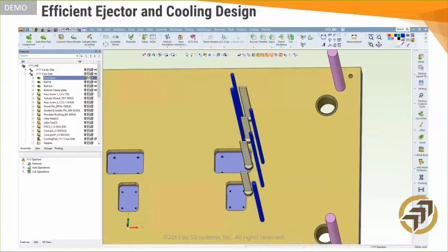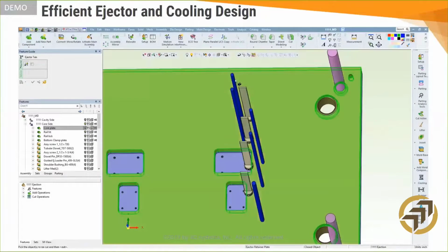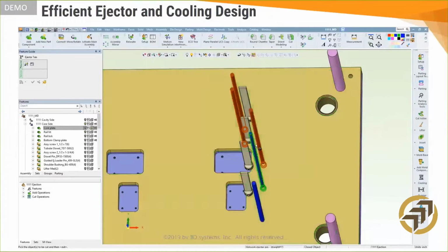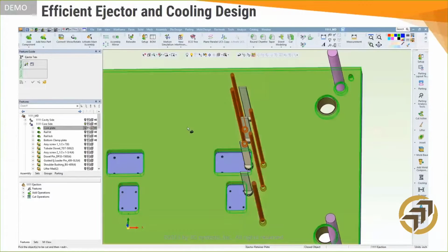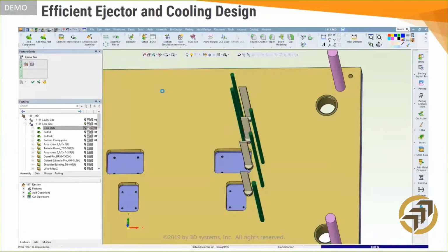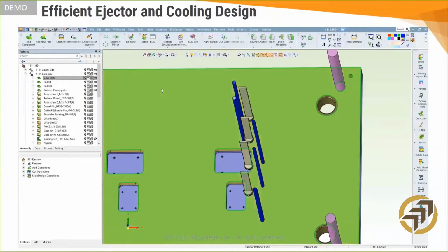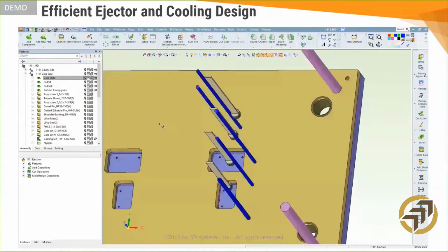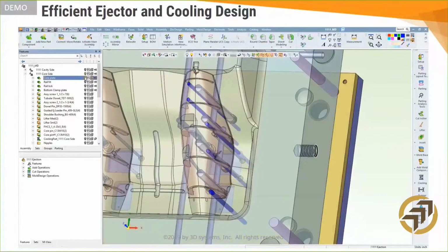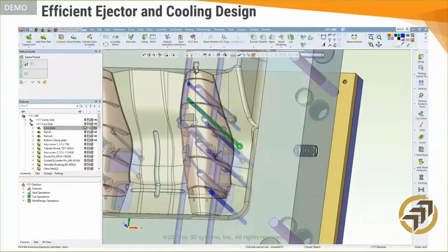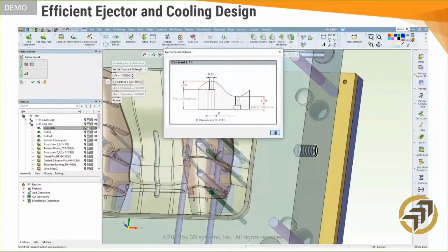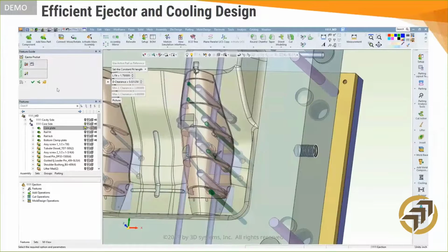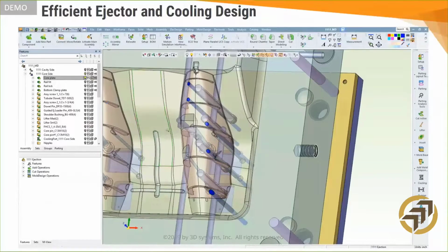Ejector pins can be trimmed flat or to the shape of the part and even have additional positive or negative offset. None of this is extra effort because the dedicated function for trimming ejector devices knows what to do. The special conditions of the ejector pin holes are handled in a similar fashion. Clearance lengths are calculated from the part surface down so that the correct hole diameter and purpose is placed in every plate in the tool.